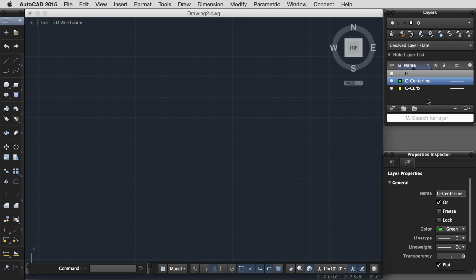Now we would like to affiliate the center line type with the center line layer. So let's use the Display Settings menu. This is going to go off the screen, so just follow the voice prompts. Then View Options, and then Line Type. Now you'll see a new column appears in the Layers panel, and I can select my center line, which I just loaded.